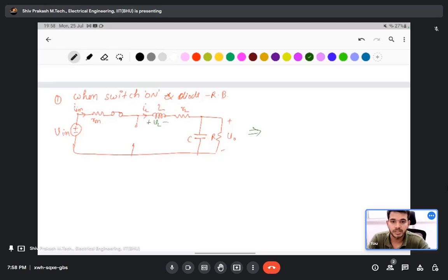In a capacitor, there is charge balance. Once the capacitor is fully charged, it stays so even when the circuit is disconnected. So you should know about flux balance and charge balance. Flux balance occurs in the inductor, where you find the volt second equation, and the current second balance equation we take in the capacitor. Then first of all we find VL.